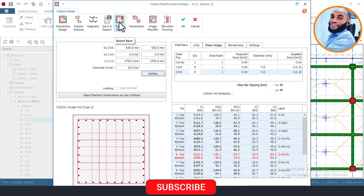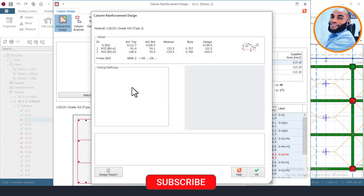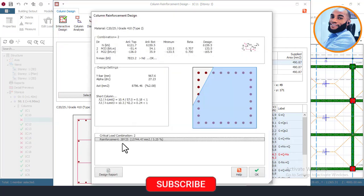And then I'll come here and click on reset bars. Always reset bars, okay? The reason is that here it is showing 12, which is not okay. So I'll come here and reset bars, and then click on interactive design here, and wait again for the design. And it is giving me the critical one, the same thing again, showing 25 and 20. So once you're able to see the size of your reinforcement for your column, that column is perfectly okay.